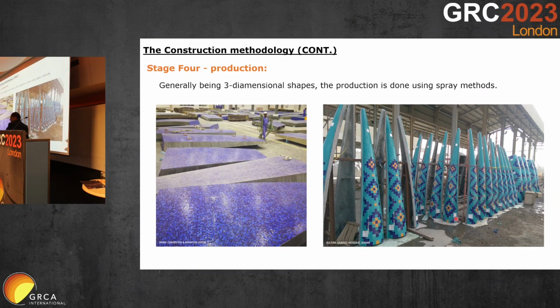This is another one, another finish. Again, these segments where you had 25 by 25 tiles, glass mosaic, they were with the mesh, and they were plain tiles. Whereas here, you had a bigger tile, these are Iranian half-baked handmade tiles, and they were with the pattern. So again, the same concept, and we had real issues again, delamination. But there was a good thing to that. The size was big, that was the issue.